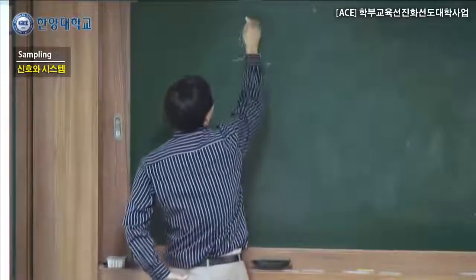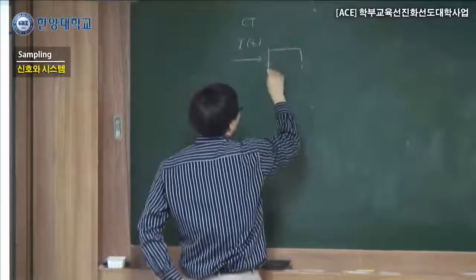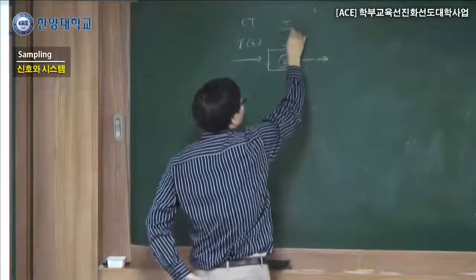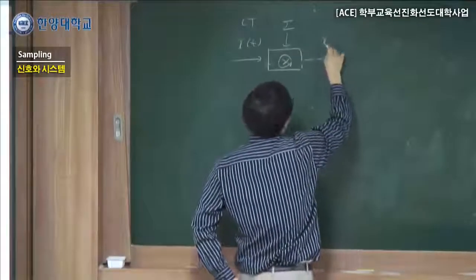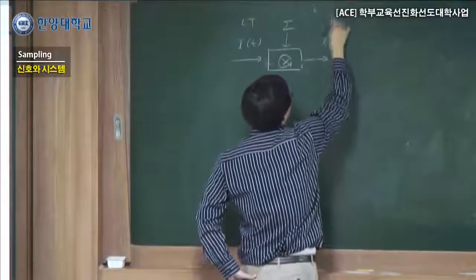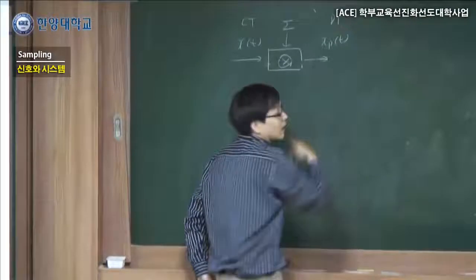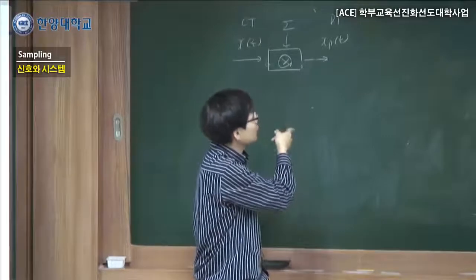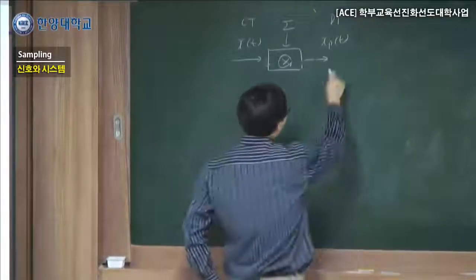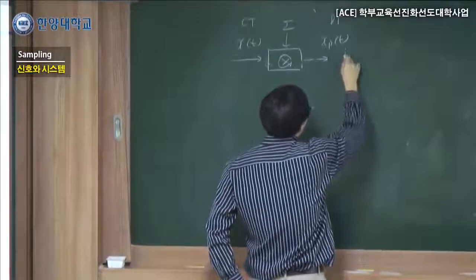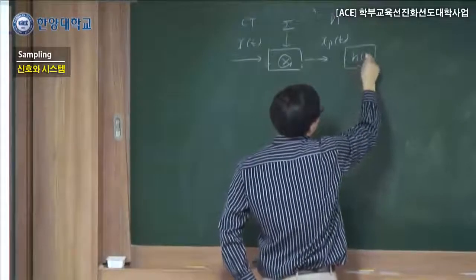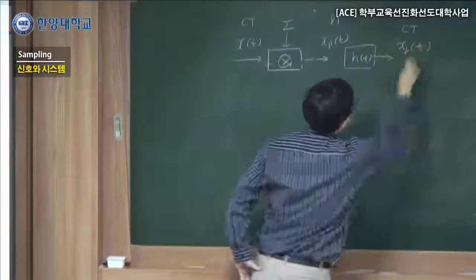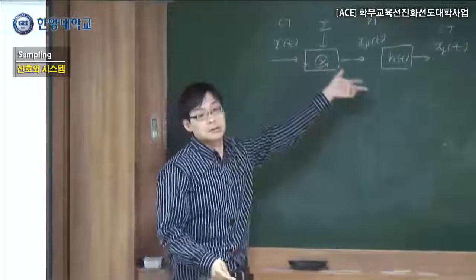We have x(t), which is continuous in time. After passing through one system, basically multiplied by the impulse train, it changes to a kind of discrete time signal, or kind of. Well, I say a kind of because, according to your question, this looks like continuous time, but actually it is discrete time. And then we use a new system called H to go back to continuous time. We call it the recovered data. So we talk about those three signals.